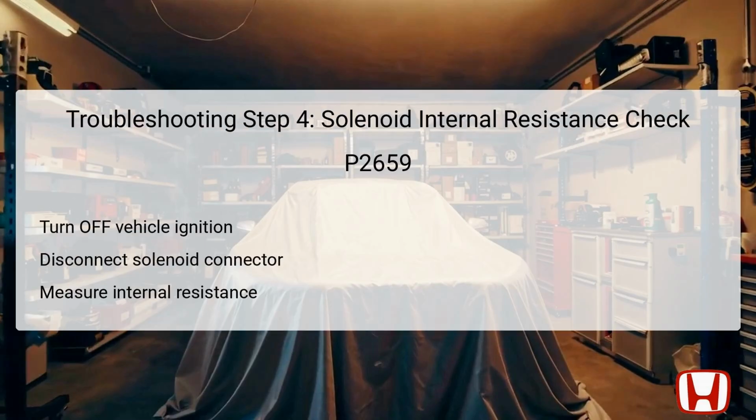undertaken. For the fourth step in the troubleshooting process, an internal resistance check of the rocker arm oil control solenoid A, bank 2, is essential. The vehicle should be turned to off or lock mode to ensure safety prior to disconnecting the solenoid connector. Following this, the technician will need to measure the resistance between designated test points at the solenoid.